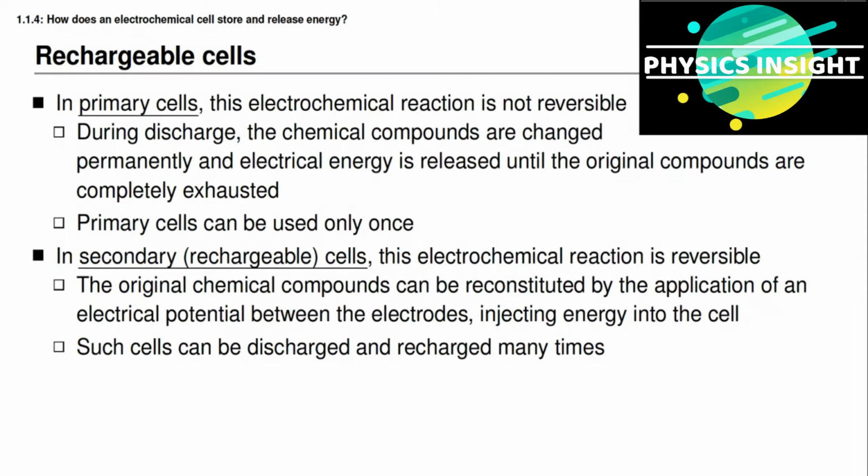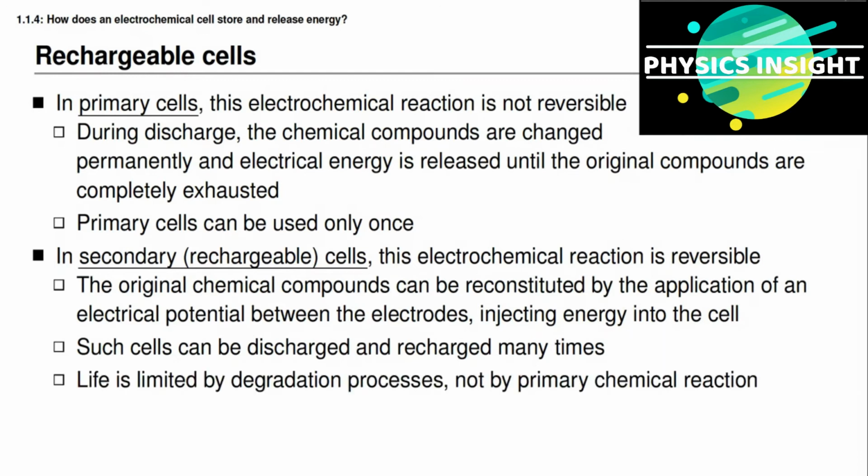And it turns out that the simple understanding we have at this point of how a battery cell discharges and recharges is true for the primary chemical reaction that's happening in the cell, but it neglects the fact that there are other chemical processes and mechanical processes happening inside the battery cell that cause degradation or aging of the cell. That is, inside the battery cell there are multiple chemical processes happening, where only one of them, hopefully the dominant one, is the electrochemical reaction that we want to happen that's releasing energy into the load circuit.